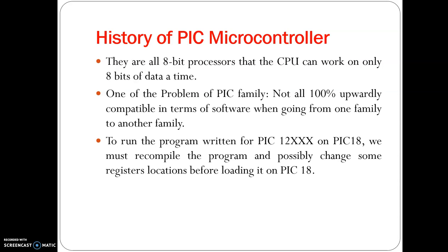So to run a program which is written for PIC12 on PIC18, we must recompile the program and possibly change some register locations before loading it into the PIC18. So I cannot directly run a program written for PIC12 or PIC16 on the PIC18. That's why it is not 100% upwardly compatible.